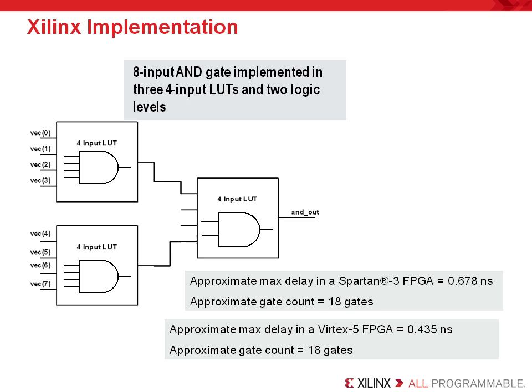Finally, as you might expect, when we synthesized this simple design for Virtex 5, we got an even faster result. Now, a lot of people would say, well, that's because Virtex 5 is built at a better technology. Well, that is part of it, but the real question to ask yourself is, how many logic levels do I expect this code to synthesize when mapped to Virtex 5? The answer is it will synthesize to the same number of levels. Since Virtex 5 has a 6-input LUT, and the design requires 8 inputs, we will get pretty much the same result that you see here.